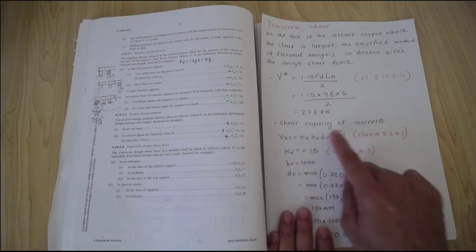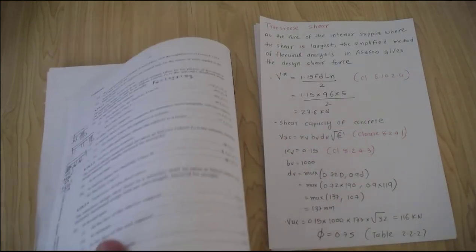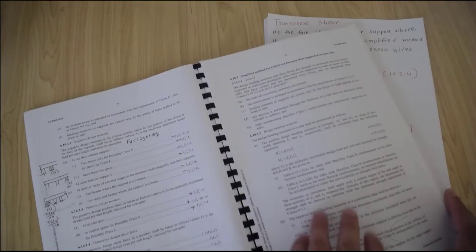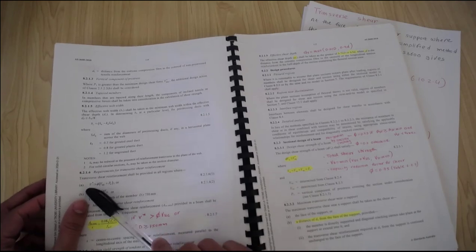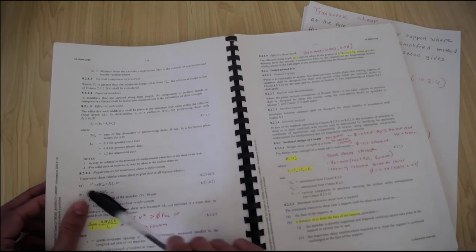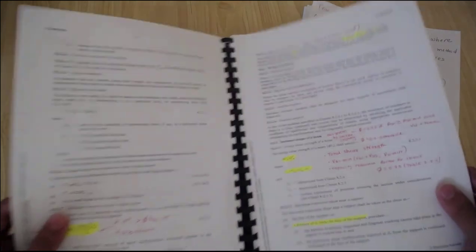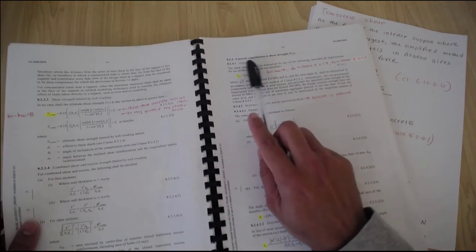Now we need to make sure whether we want to provide shear reinforcement or not. The equation given here says that if your design shear force is greater than 0.5 phi Vuc, then you require the fitments. Otherwise, you don't require the fitments. So now to calculate the concrete shear capacity,